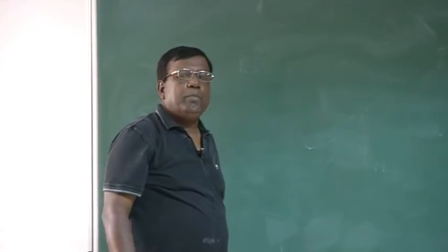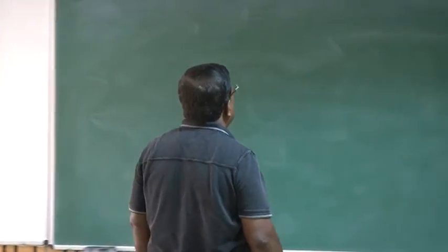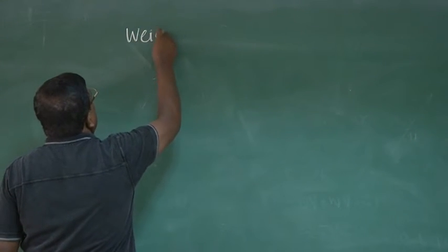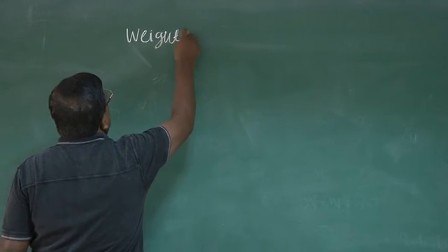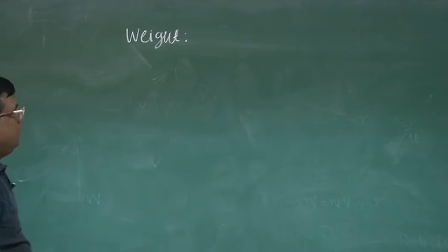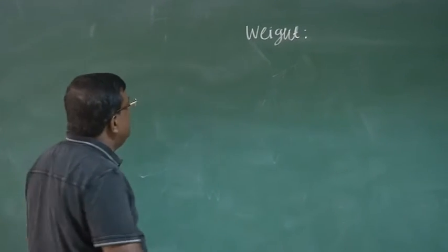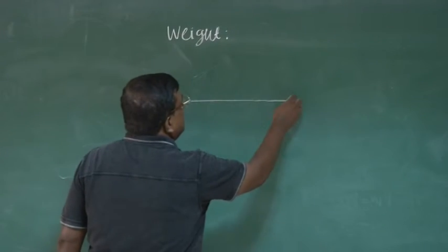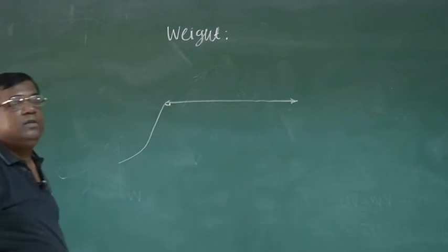So what do we do? I again take the weight of the airplane and I say, let us go for a climb. Before I do the experiment, I do the weighment, I take the weight of the airplane with passenger, fuel, and the pilot in command. Now the pilot will go and establish himself at a particular altitude.